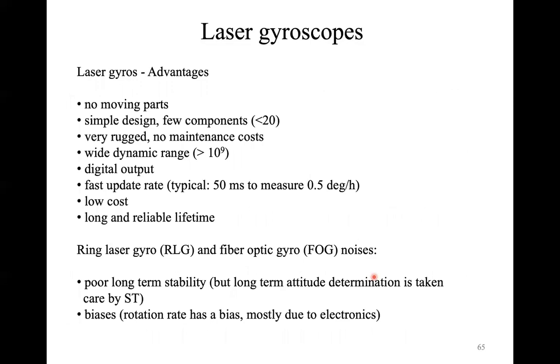So what are the main advantages of laser gyroscopes? Why do we need to use a much more complicated technology compared to mechanical gyroscopes? Well, you have a lot of advantages. The main advantage, as I said, is that you don't have any moving part.